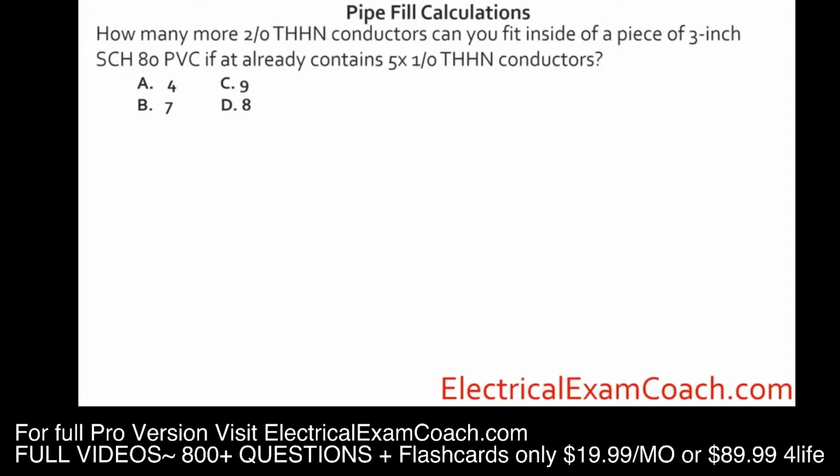It's assuming that you've already learned how to use these tables. I'm not going to be showing them on the screen. How many more 2/0 THHN conductors can you fit inside of a piece of 3-inch Schedule 80 PVC if it already contains 5 1/0 THHN conductors?